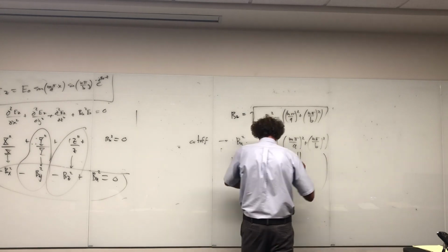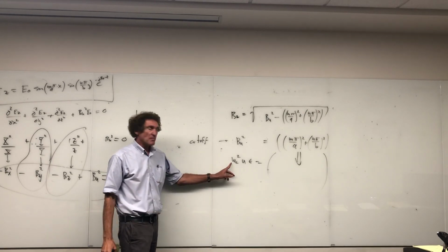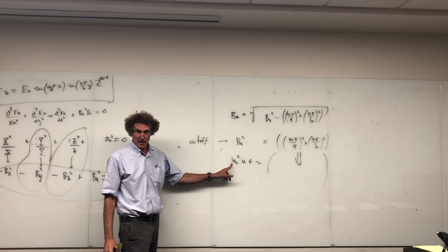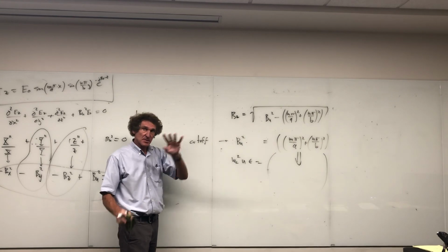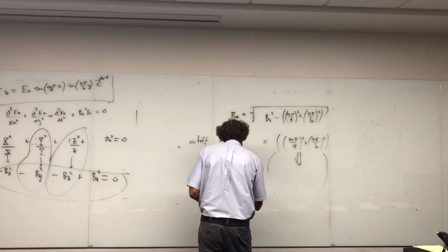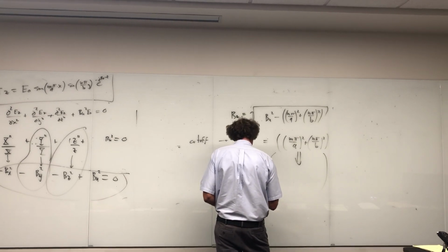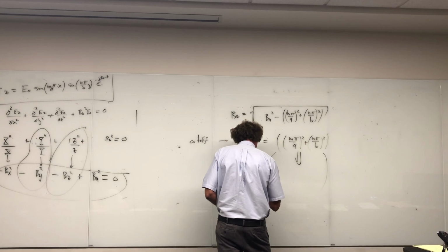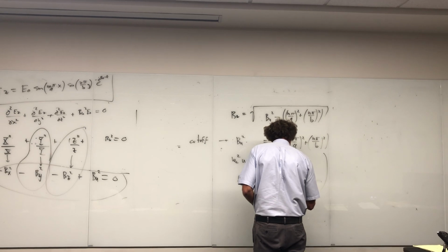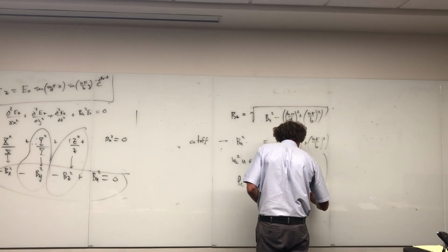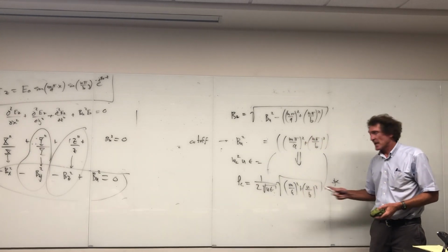I'm just going to put an arrow here because I'm out of time. And listen now. If I take omega c and make it 2 pi fc, then square it and take it to that side, I'll be able to cancel the pi's. Here's where it comes to, because I am about a minute over. The cutoff frequency is equal to 1 over 2 times the square root of mu epsilon, this is in your book, times the square root of m over a squared plus n over b squared. And this is the cutoff frequency for a waveguide, where m and n are called the mode numbers.